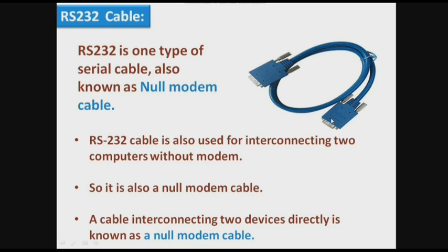This is the RS-232 cable. So this part will connect to one PC and this one is used to connect to another PC to make interconnection and to share information between them. There is no modem, so this cable is also called a null modem cable.